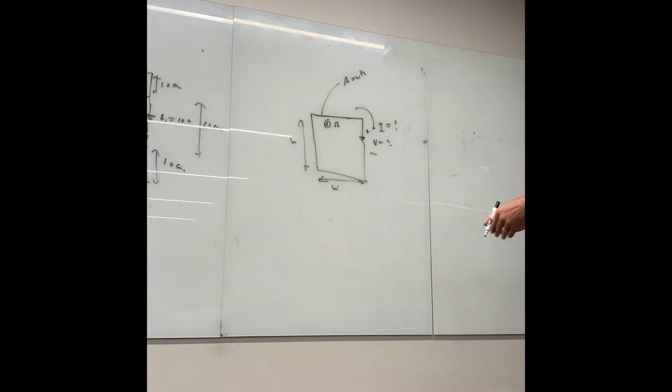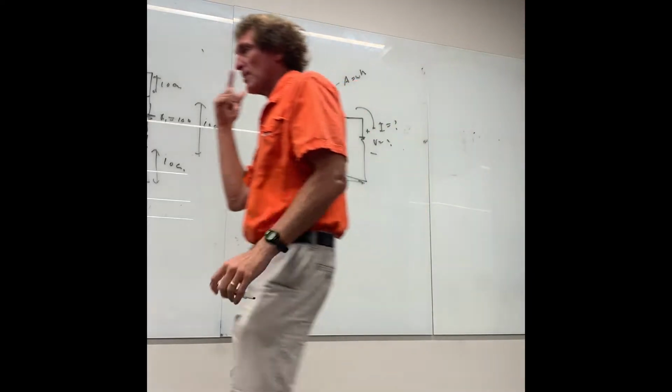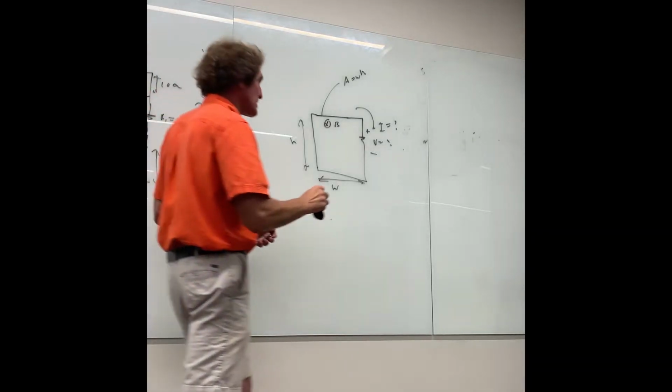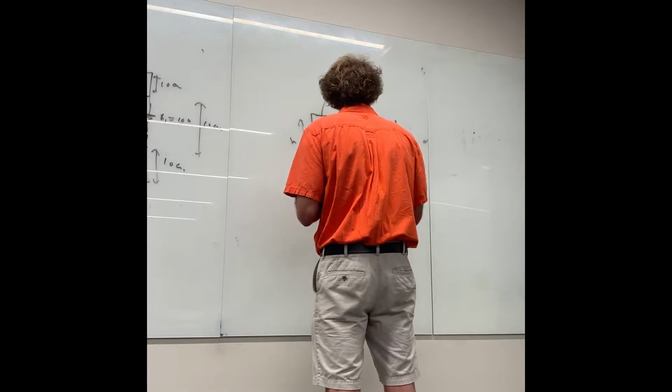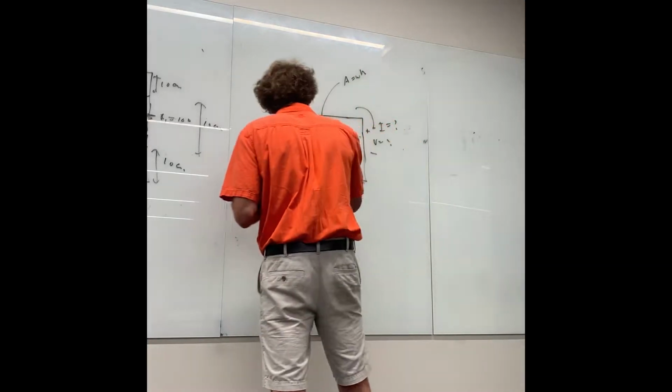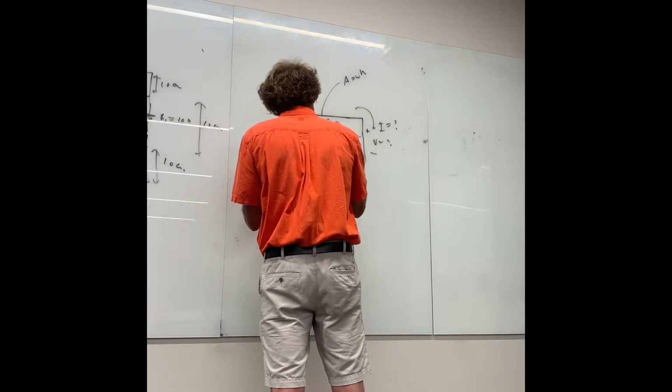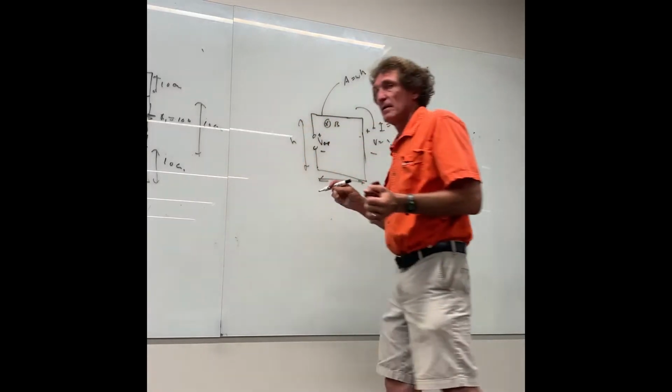Now, the way you go about this is first, do the problem the way I set it up originally. You assume that this thing doesn't have a resistor in there, get rid of the resistance, and assume it has a little break here, plus to minus. And that's the voltage you're going to get first, that V_EMF.